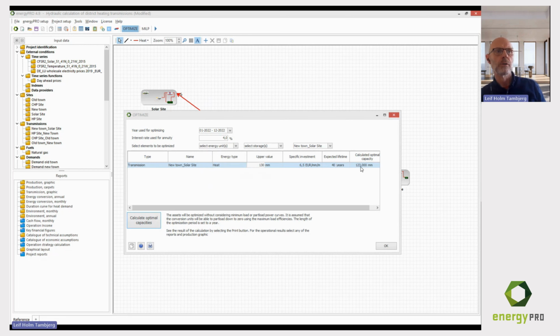Okay, now it's 123 millimeters, and that way, of course, the jump is a lot smaller now. So maybe you can argue, okay, I'm about there, and also, of course, maybe you cannot most likely have a pipe with this specific diameter. You'll need to say, okay, it is in this area, and then you use an available pipe diameter in your calculation from now on.